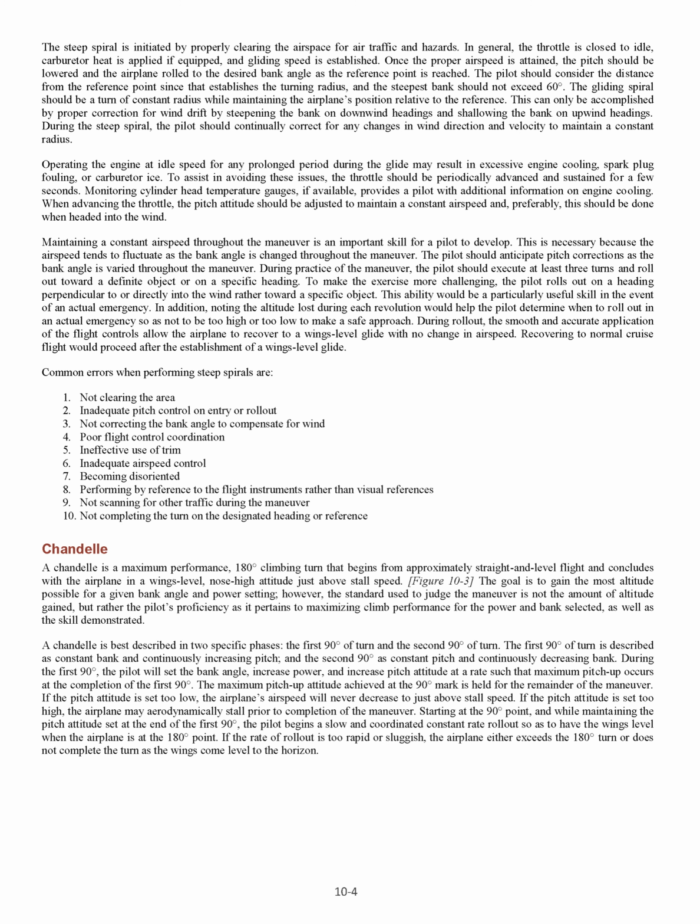Chandelle. A chandelle is a maximum performance, 180 degrees climbing turn that begins from approximately straight and level flight and concludes with the airplane in a wings level, nose high attitude just above stall speed. The goal is to gain the most altitude possible for a given bank angle and power setting.